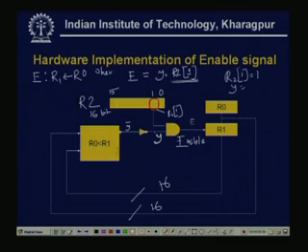And in this way it will occur. So, mainly the main point is that the register R1 has another input, and this is the enable signal, a control line, and whether the register transfer will occur or not is controlled by this E line, that enable line.